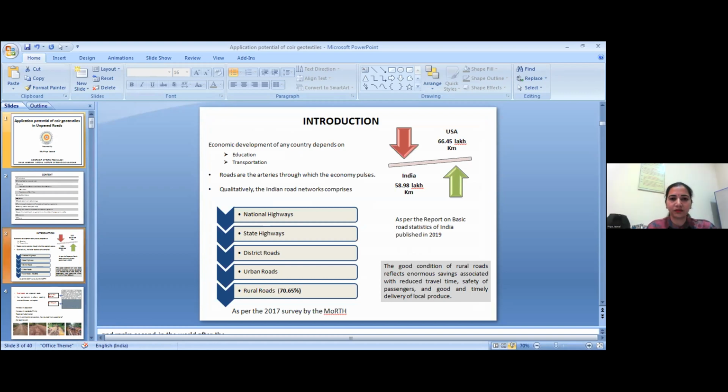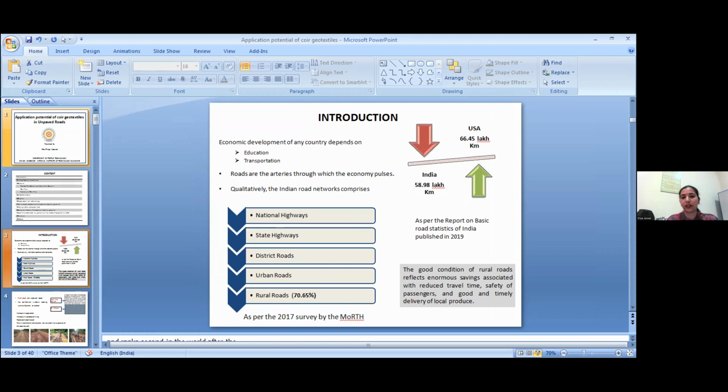Okay, we are in the third slide now. Yes, so I covered what unpaved roads are. These are pictures of unpaved roads. And the problems faced by unpaved roads are given here: loss of mechanical property, increase of load, poor structural integrity, subgrade softening, development of a rough riding surface, poor bearing capacity, generation of surface cracks, rutting, and potholes. All these problems further result in increase in maintenance cost, and it hinders the traffic also.